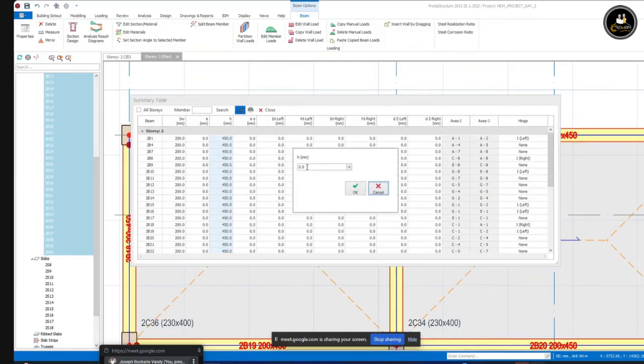Now, there is the icon that's showing moving downwards. We are only on this one. Yes, that one. Click on that. So move down, choose a beam depth that you need, 300.